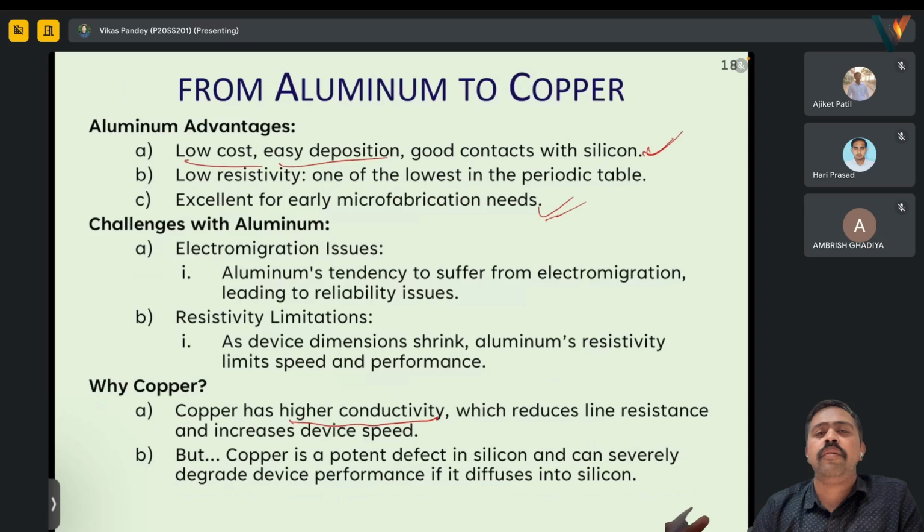So how is it done? Titanium nitride is deposited between the interconnect and the silicon or silicon dioxide. So before depositing copper, a layer of titanium nitride will be deposited, and then the copper will be deposited. This ensures that we are getting the conduction from copper, as well as copper remains on top and does not get inside the silicon. And there is a process, the damascene process, that is used to connect the silicon layer with tungsten wire to a metal.